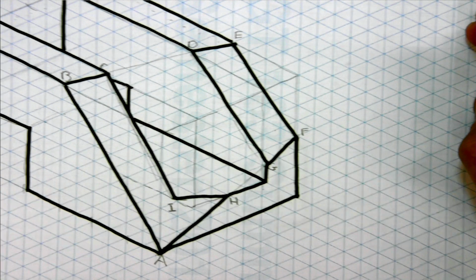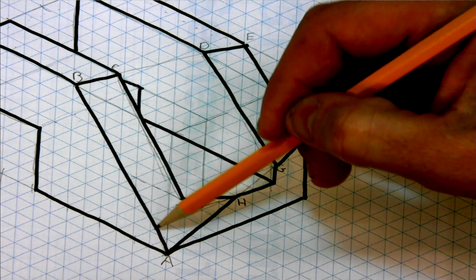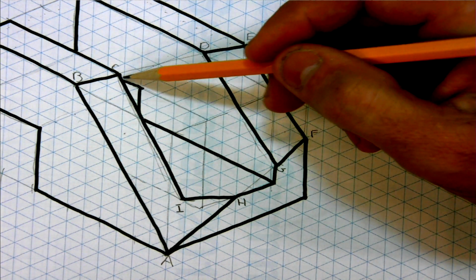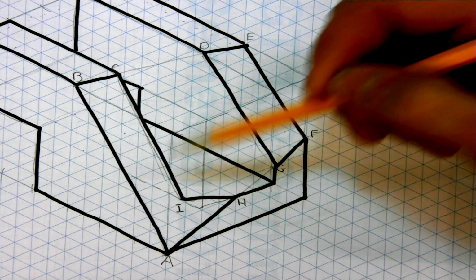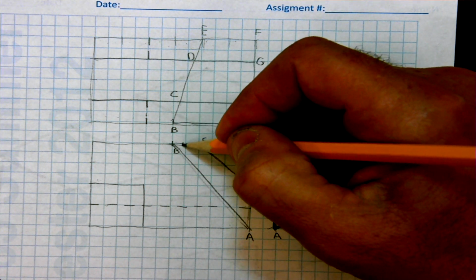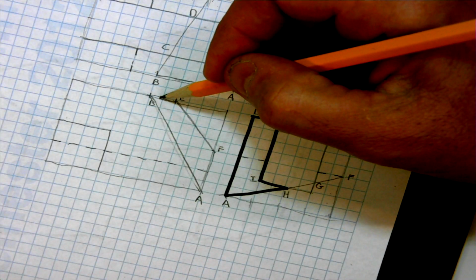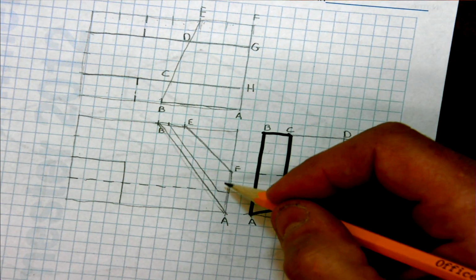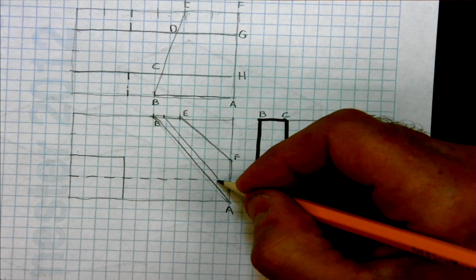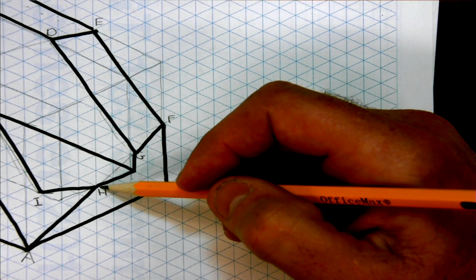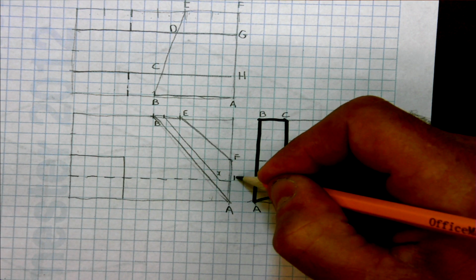But now if you look over here, we know that this line, because the oblique plane intersecting the frontal plane, and this and this and this are all parallel, so I know where C is at. So I can project C down to I in this view. I got C here, I project C down to here, and if it's parallel to these other lines, I'm going to come down right in here. Where it hits at this level, 2 up from the bottom, defines point I right here. I then goes back over to H to the right, then H goes to A.